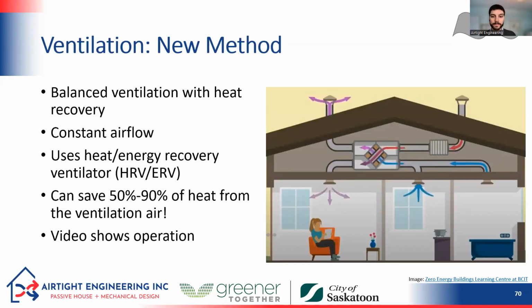The new method of ventilation is far superior in many ways. So now we're using a unit that's called an HRV or an ERV. That stands for heat or energy recovery ventilator. And this is now balanced ventilation. So this unit is designed to run all the time, slowly, just in the background. And it's providing constant fresh air. So instead of just waiting till you take a shower to get some more fresh air into your home or needing to open the window, which is great in the summer, but less helpful in the winter, we actually get constant fresh air.